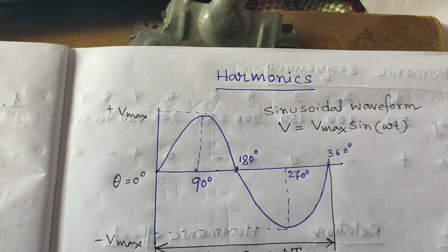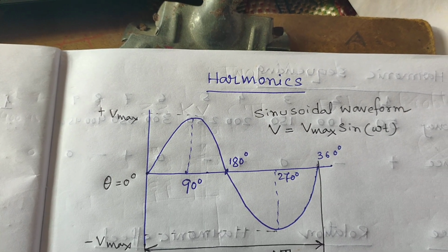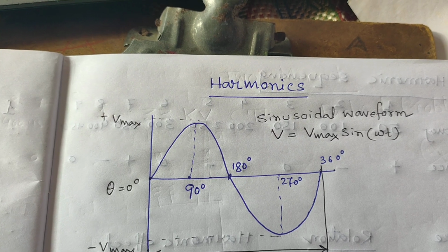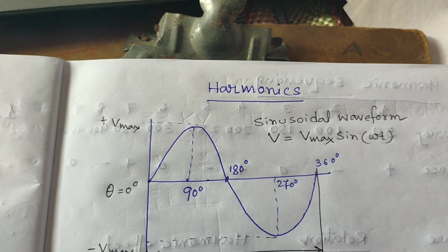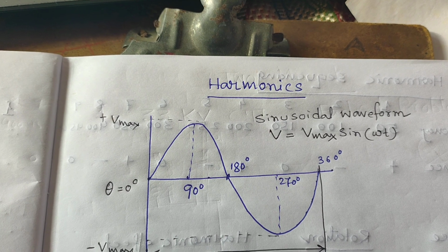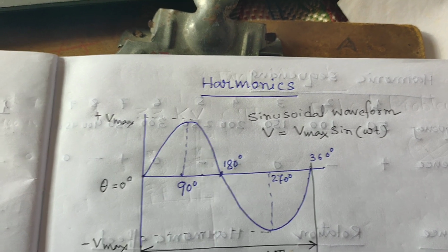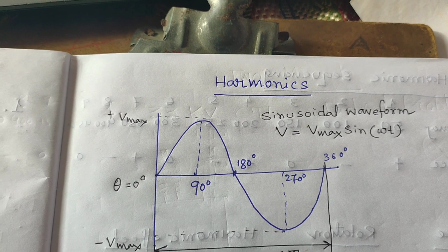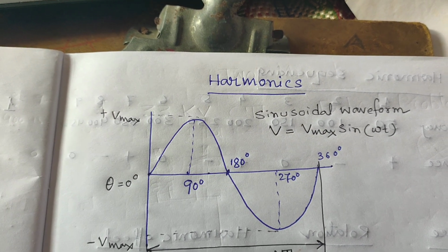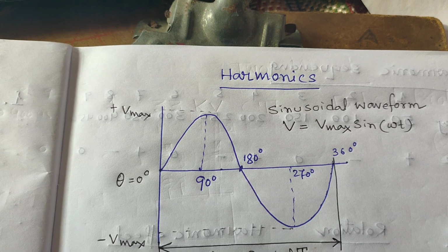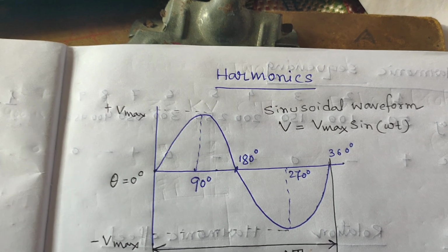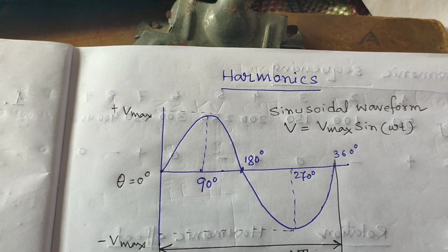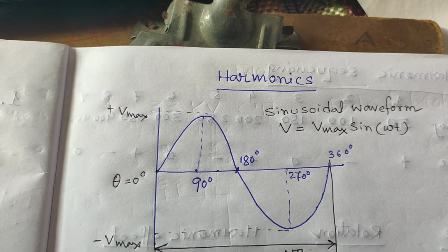The amount of waveform distortion present, giving a complex waveform its distinctive shape, is directly related to the frequencies and the magnitudes of the most dominant harmonic components, which are harmonic frequencies that are whole integer multiples of the fundamental frequency. So the most dominant harmonic components are the lower order harmonics from the 2nd to the 19th, with the triplen being the worst.